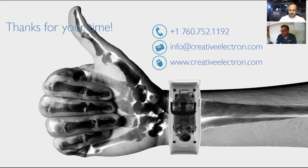But moving a capacitor 2 millimeters to the right wouldn't affect it. There are some more complicated things, like communication protocols, where the trace has to be a certain length. That will be more complicated. But for passive components, it wouldn't be an issue.